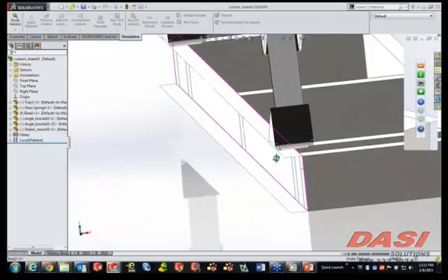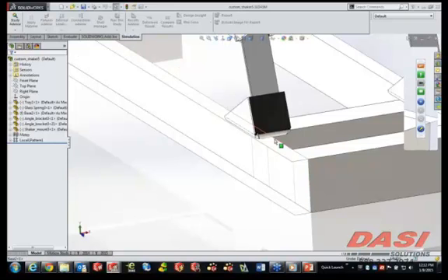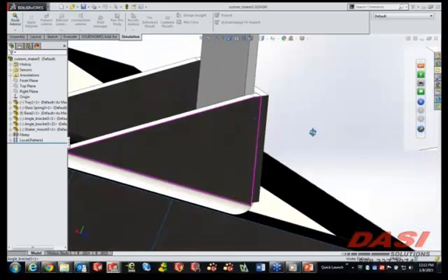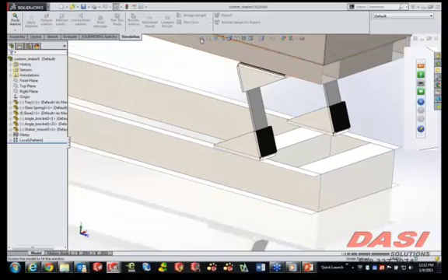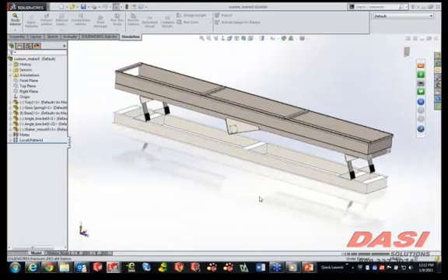Down here we have surface modeling, so zero thickness geometry in effect, and then here we have a sheet metal part. Also thin wall geometry, but this one is solid. It does have thickness to it. So this is handled in a couple of different ways with this release. When we're setting up any type of a simulation using thin wall geometry, generally we're using shell meshing.